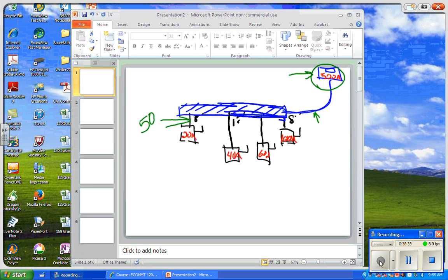Now, occasionally, we'll see that in a minute, the load will be larger than the tap rule minimum. And what do we go with? Go big or stay home, right? We're going to go with the bigger one. Whenever the tap rule minimum is smaller than the actual load, we go with the load ampacity. Everybody clear on that? Anybody got a question about that? You're going to get tripped up on that in the future, trust me, so make sure that you get this clear in your head. Whenever there's a tap rule minimum ampacity and the load is larger, we would go with the load ampacity for the tap conductor.